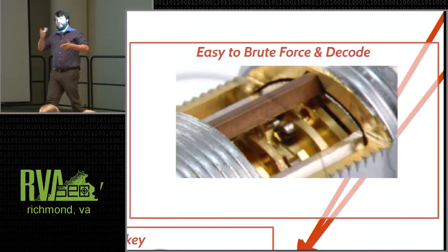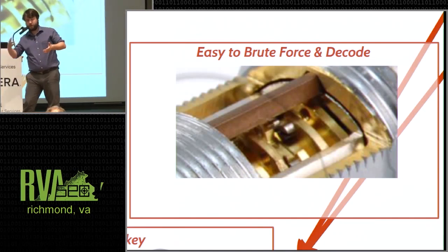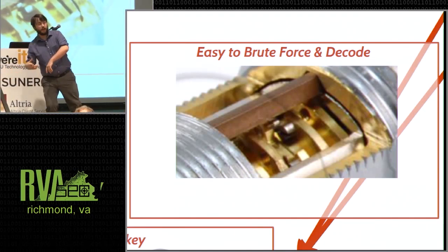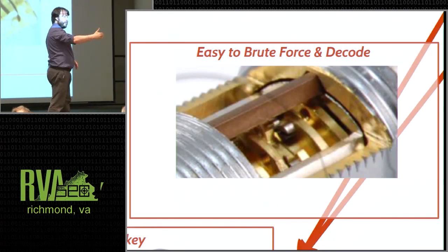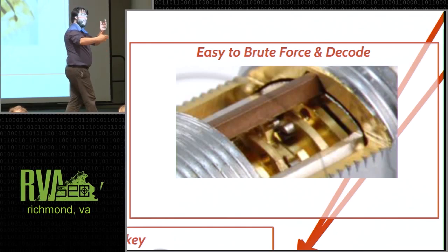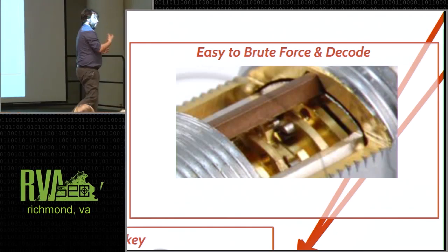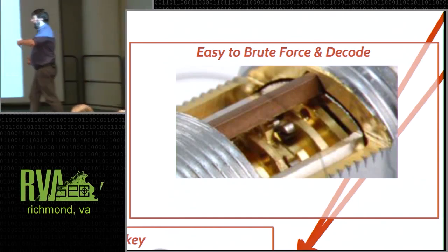This is why when you're dialing the lock on your locker or you're dialing the lock on your safe, you have to move however many times in this direction, and then one fewer times in this direction. What you're doing each time is leaving a wheel behind that's positioned. And then you go back in the opposite direction, you pick up however many wheels you need to, you leave the next wheel behind, and so on and so forth. And this is how you get them all aligned.